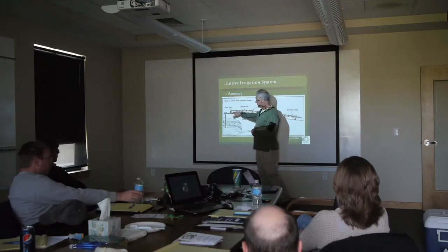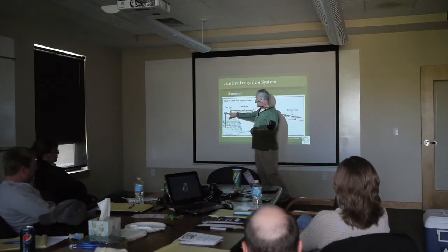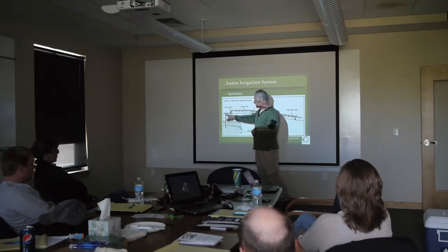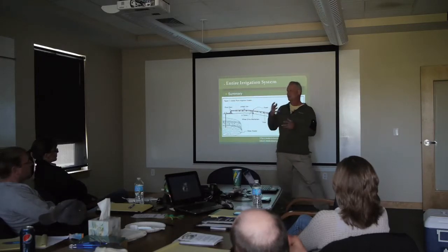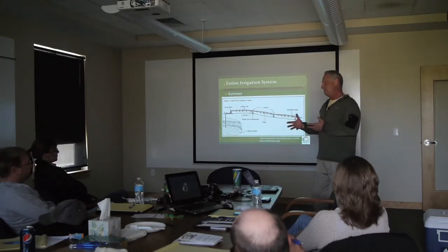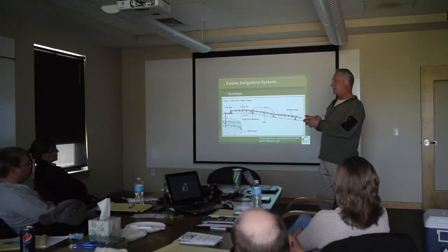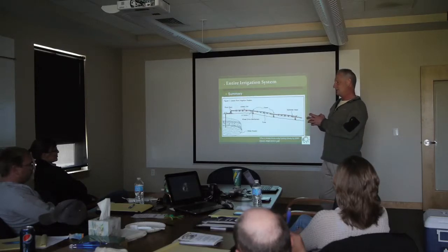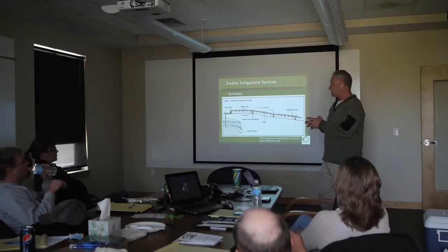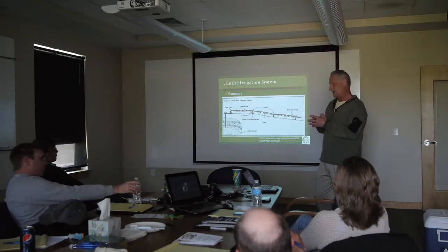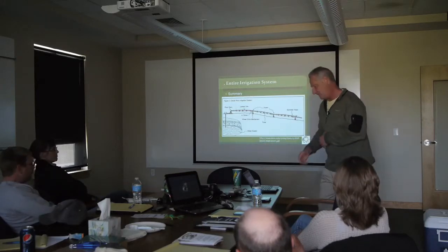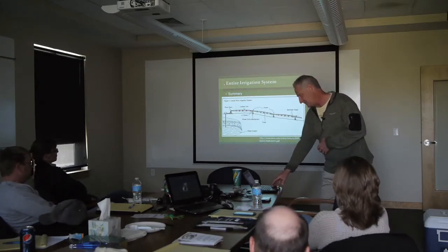All the little elbows and fittings and stuff. This loss here, this is vertical. Add those in. It's volume and pressure. And compare that volume times the pressure in horsepower or watts, probably watts, should be the size of that motor. Okay, so that's how those match up.